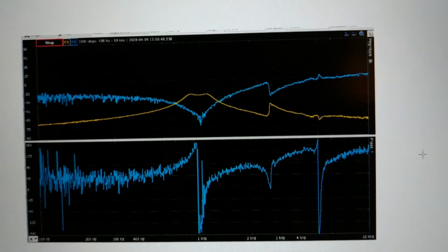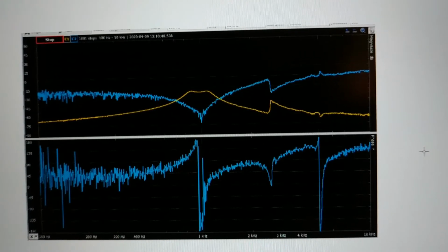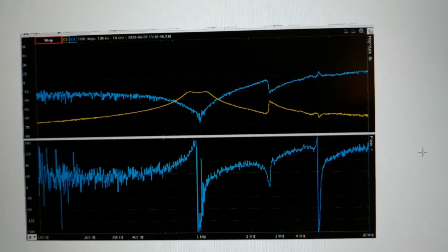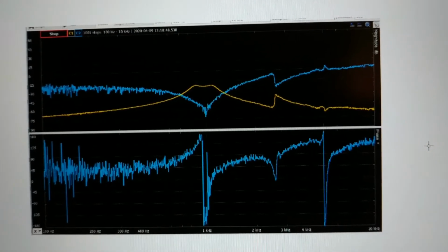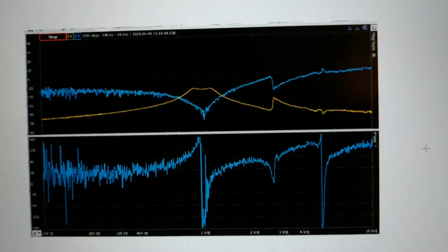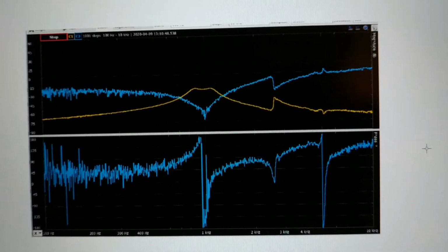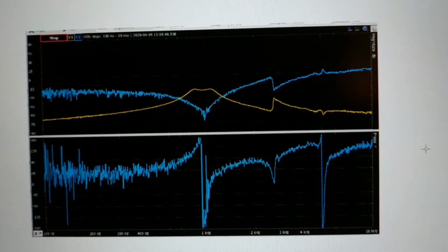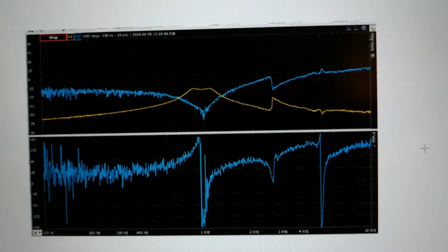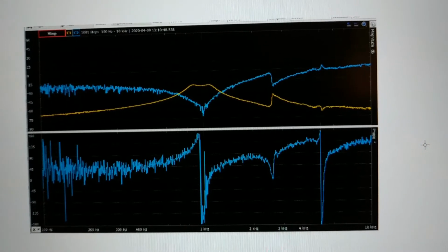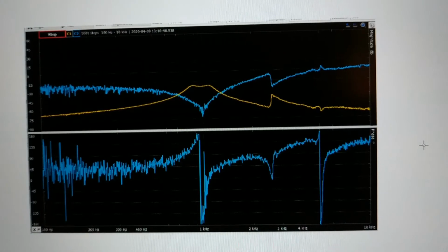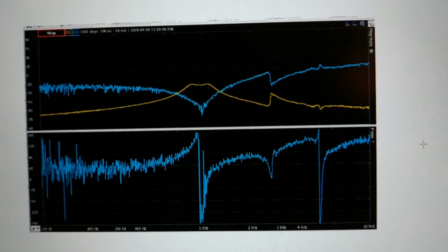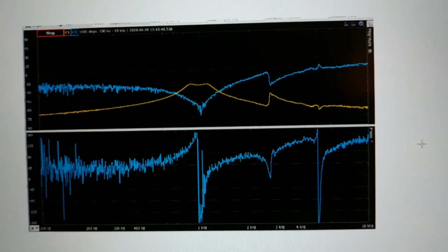The signal output from the analog discovery device was routed into a piezo transducer for this test, instead of directly into the filter. The microphone was then set up to pick up signals from the piezo transducer, then feed the signals into the filter. Doing so allowed us to generate the Bode plot shown here. It is noticeable that there is a sudden spike in the Bode plot at around 2.7 kHz. This, however, was due to resonance in the piezo transducer and not due to the filter itself.